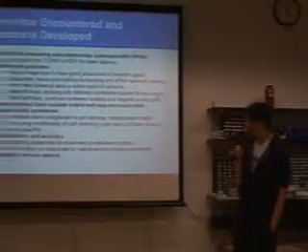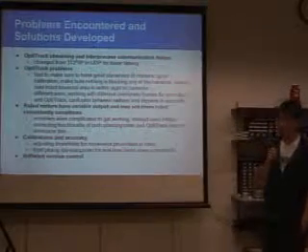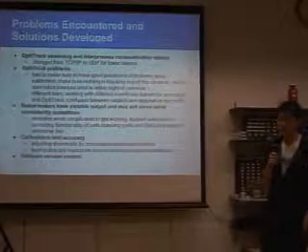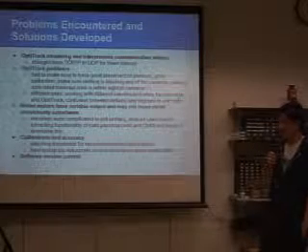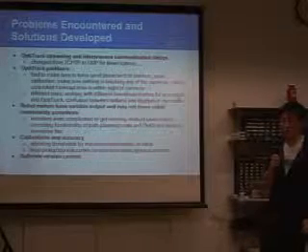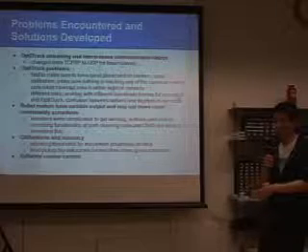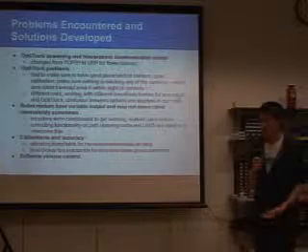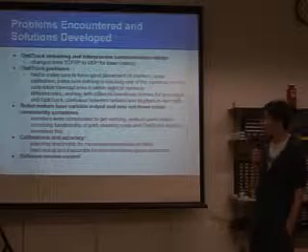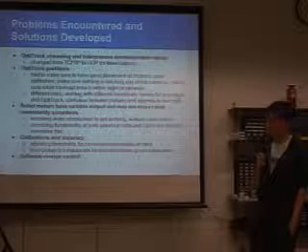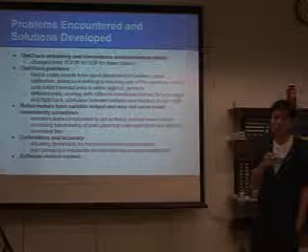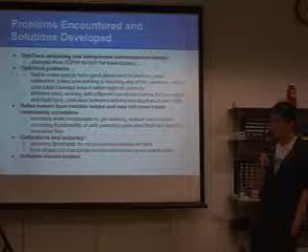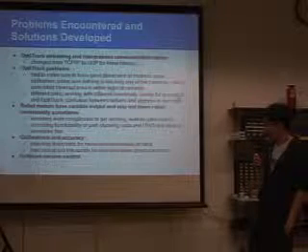Okay. All right. So the problems we encountered when trying to implement all the details. First of all, the OptiTrack streaming was not very reliable. If, like Mark mentioned, someone walks while the OptiTrack is streaming data, then we'd probably lose the robot. Second, there was a pretty long latency when we were trying to implement the networking code with TCP protocol. So we changed it to UDP for lower latency.